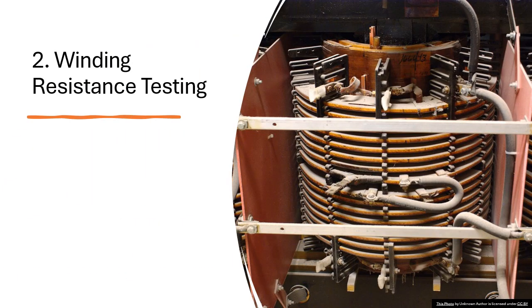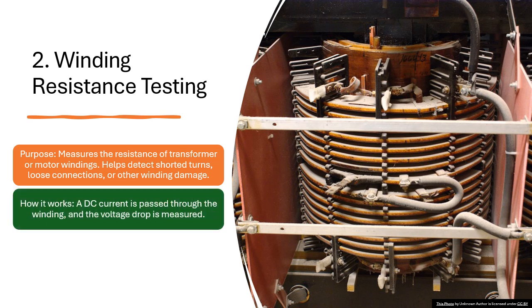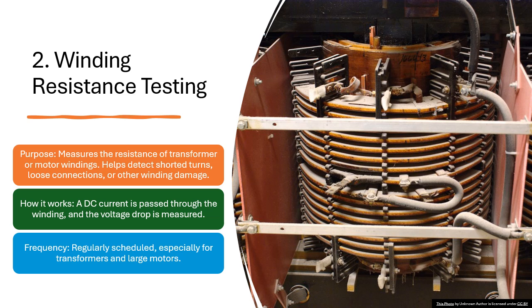2. Winding resistance testing. Purpose: measures the resistance of transformer or motor windings. Helps detect shorted turns, loose connections, or other winding damage. How it works: a DC current is passed through the winding, and the voltage drop is measured. Frequency: regularly scheduled, especially for transformers and large motors.